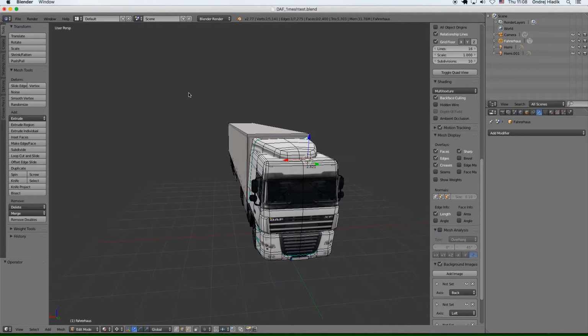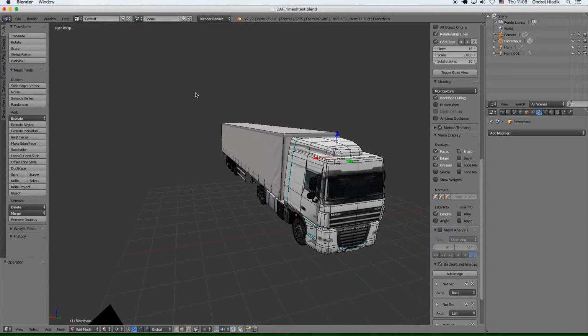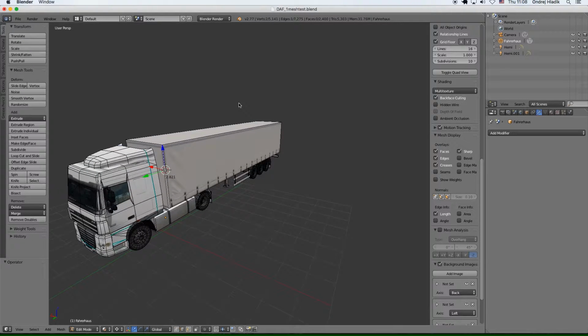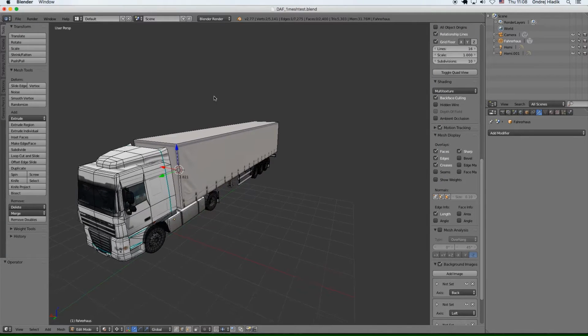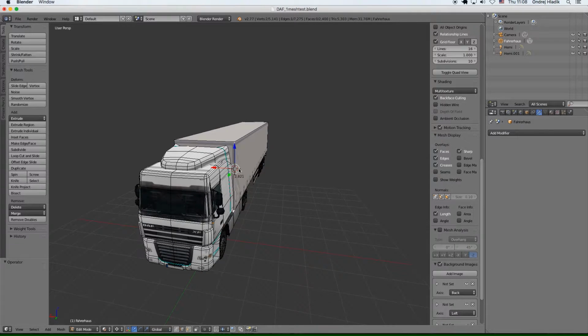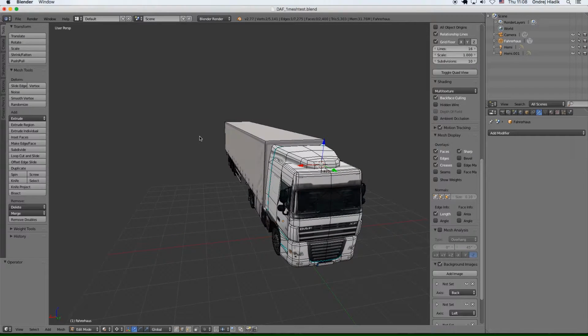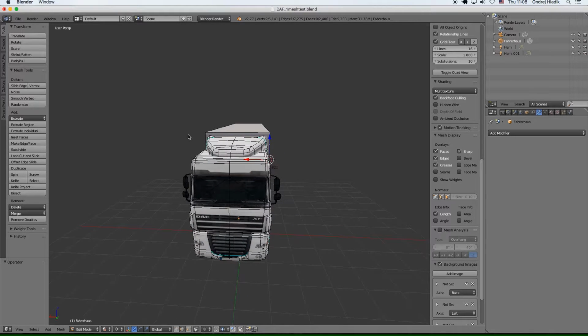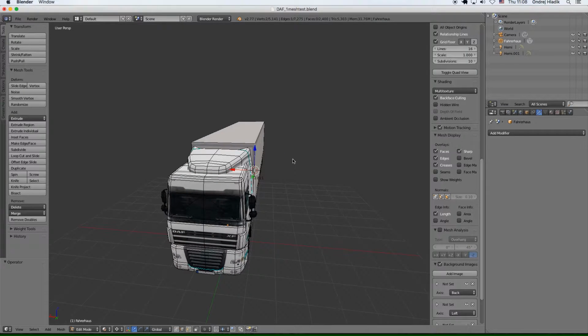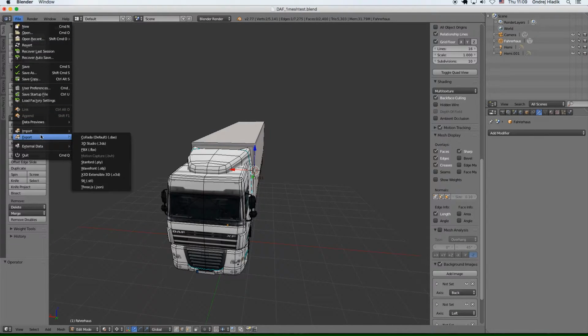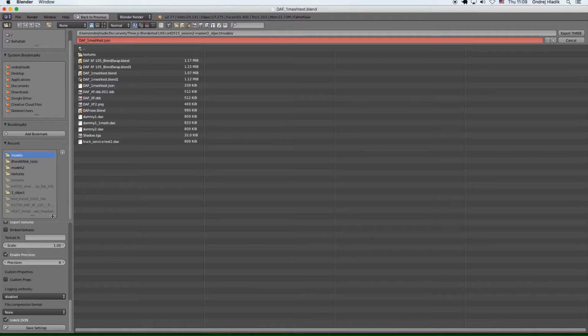So in this example I am using Blender, and I have this object here. Now to import it in the browser in BellaDati extensions, I will export this model. So here in File, Export, and there you can see that there is a 3JS option which will export the model to JSON. The important thing is that I also want the texture to be exported.